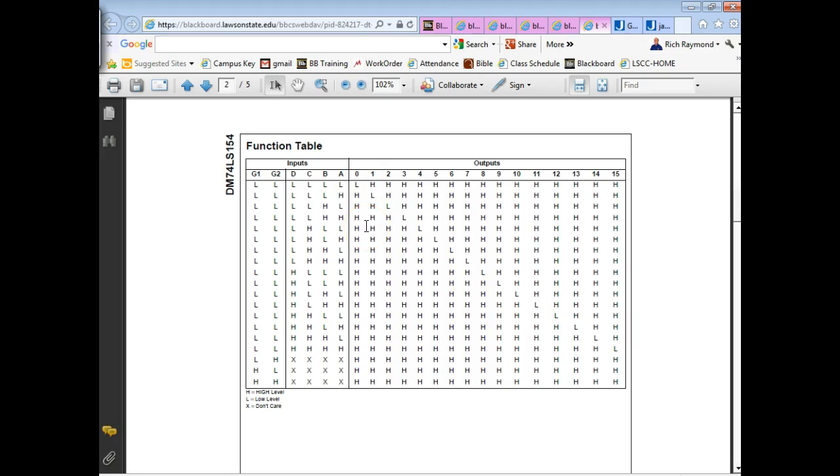You see that? If I put a binary 1 on the input, output 1 goes low. So being low active, by the way, is very, very popular. Can anybody tell me why? Why is most of these guys' output a low for a true instead of a high for a true? So this is a true output.